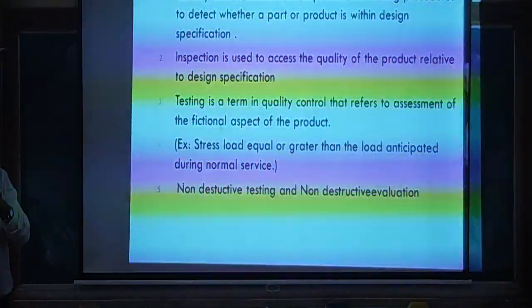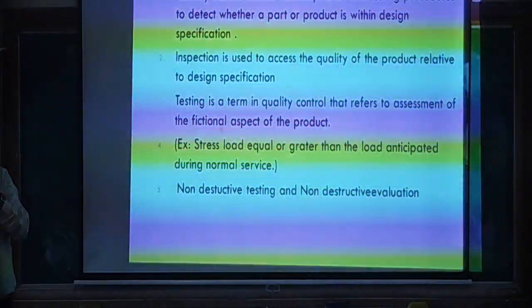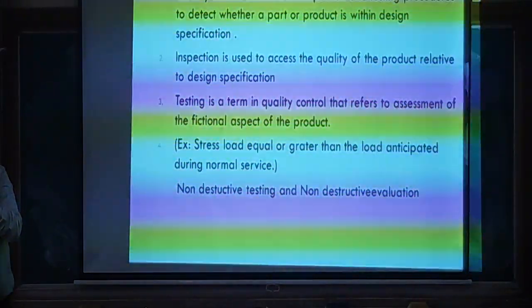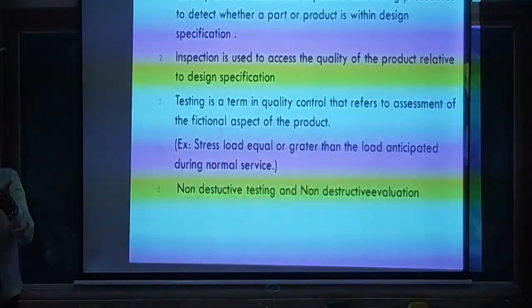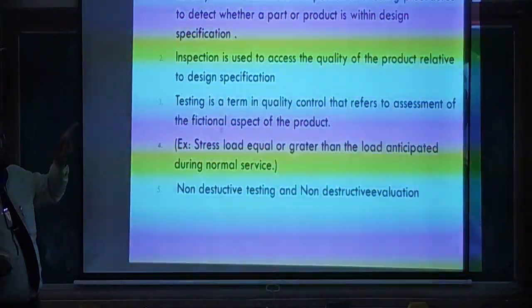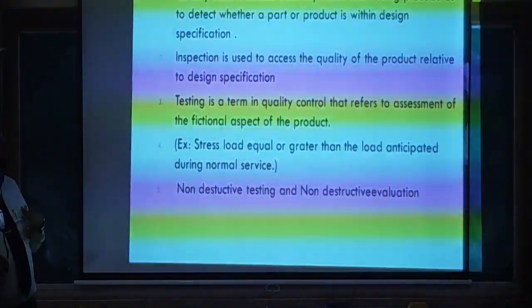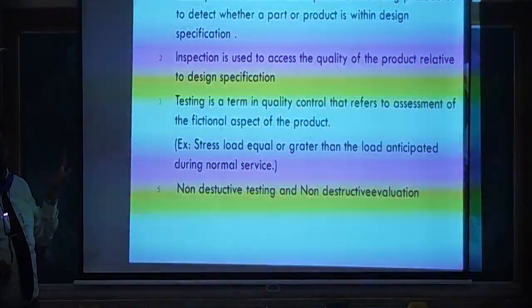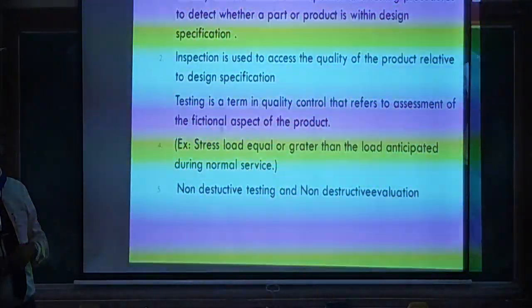Then comes your leak testing, then comes whether the part fits according to the quality standard, that is your fitment: whether it is an interference fit, a transition fit, or a clearance fit. So that we test in the testing procedure. As per the design specification, whatever the design specifies, whether it is there accordingly or not, that we are checking.